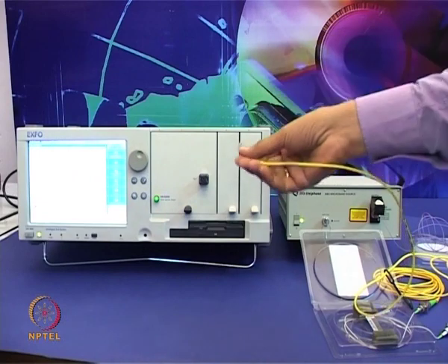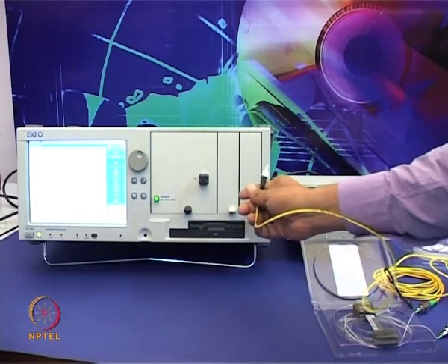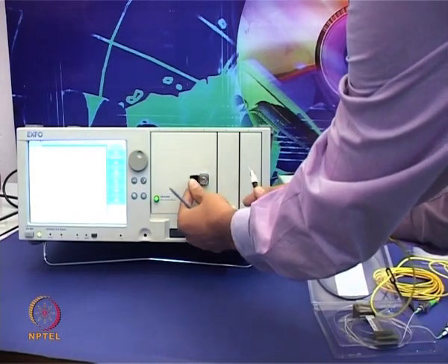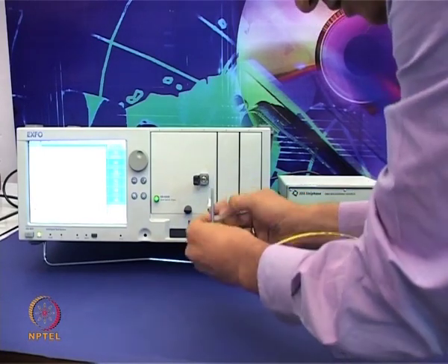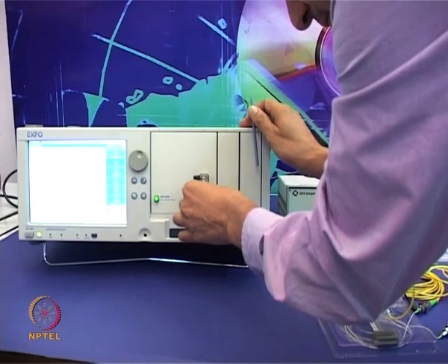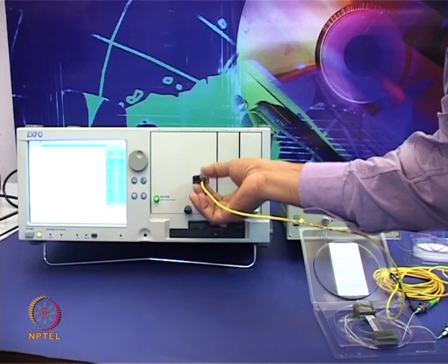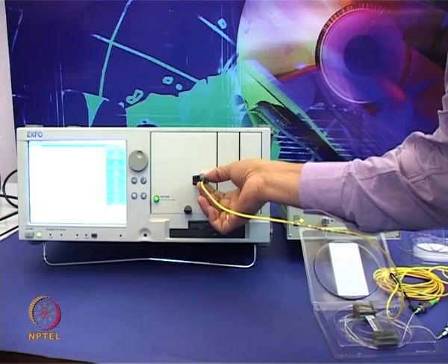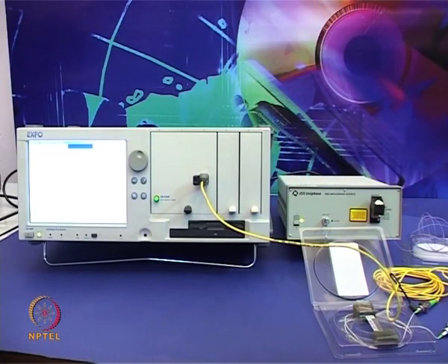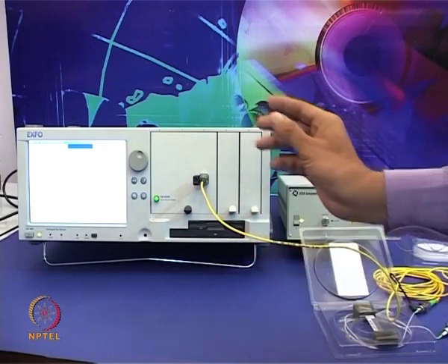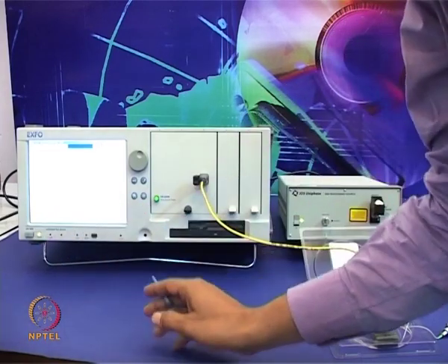An optical patch cord is being connected to the input of the spectrum analyzer. The patch cord consists of a notch which has to be matched with the input, which will be demonstrated clearly in the latter part. It has to be twisted properly till it gets fixed to the input. The green light on the screen shows the initialization of the spectrum analyzer.